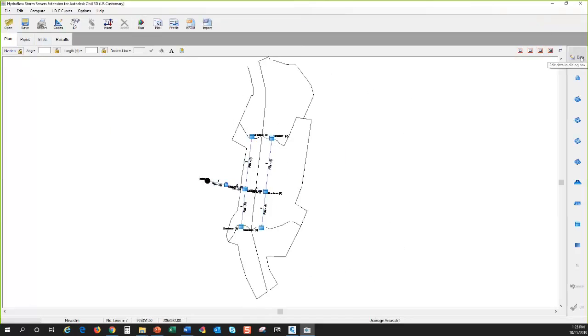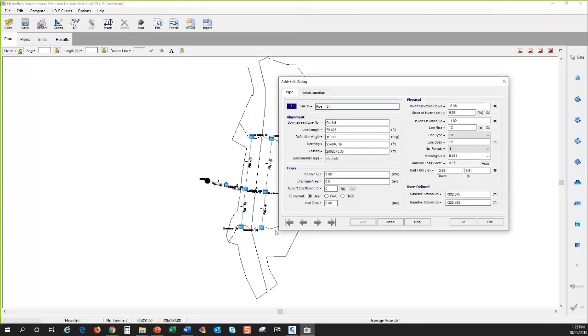except for this data. This data dialog box, when I click it, this is how you go through and start inputting information in here. Everything's been laid out in Civil 3D, but when you come in here, pipe by pipe and junction by junction, there's information you'll fill out in here to get your rational equation calculations done for your time of concentration and your Q values. And we'll go through this in a few minutes too.